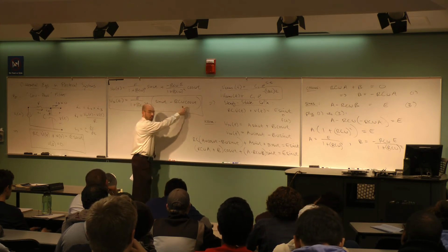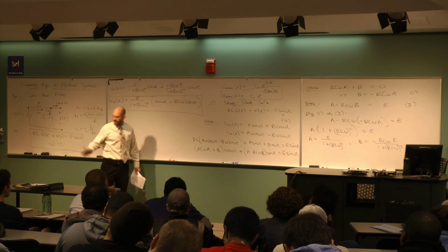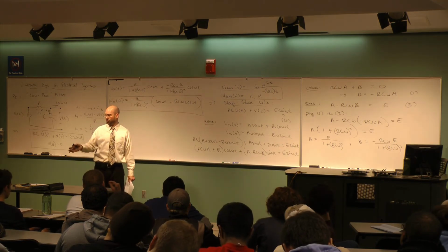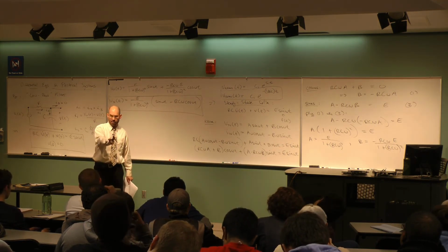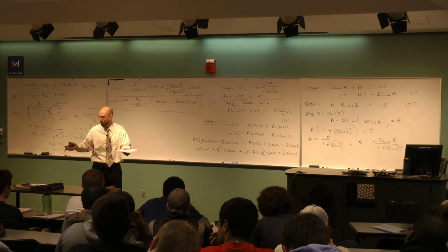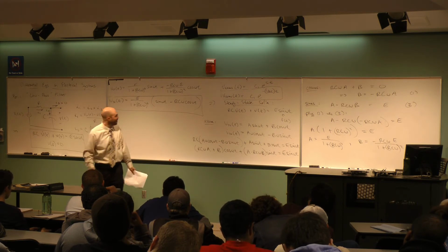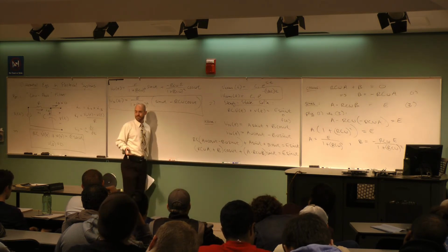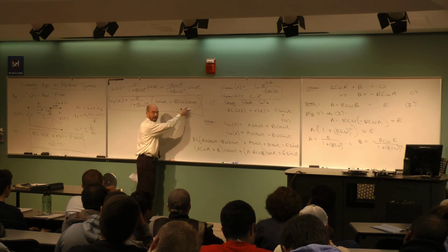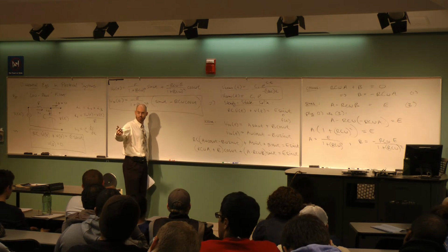It's the same frequency. So it's, you know, this steady state solution by itself, not like the spring mass we just talked about, where one was root k over m, the other one was omega, two different frequencies. I can't combine it in any way, and it does weird stuff depending upon the value of omega. This doesn't do weird stuff. It's omega here, it's omega there. It's a sinusoid, sine or cosine with what?